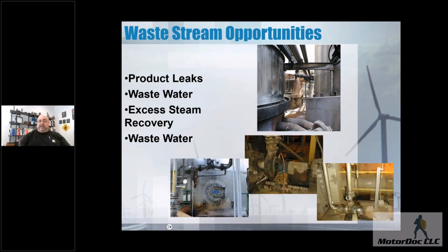I don't know if I have this in a slide. There's only a couple more slides I'm going to cover, and then we're going to get into the tools. But this is the mash pump. So a buyer made a decision. It wasn't an engineering decision to go from a double cartridge seal to a single cartridge seal. Because they were replacing these every 12 weeks or so, they swapped it over to a single lip seal to reduce the cost for the every 12 weeks, and they were replacing them now every third week. And the maintenance staff got so tired of replacing them that they just stopped.